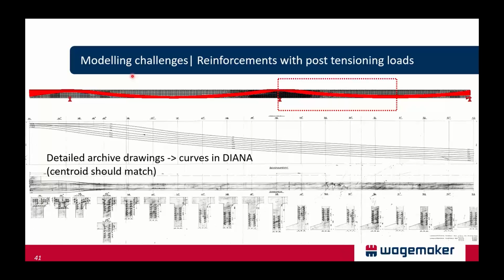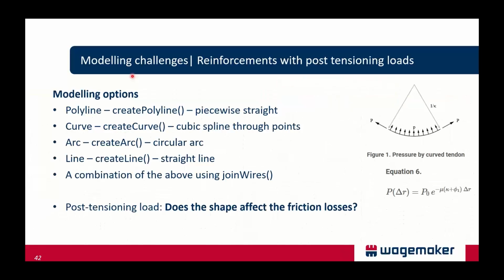If you put these curves in Diana, or put these individual tendons in Diana, you want to do it as accurately as possible. At least the centroid at each location should match the archive drawings, but preferably the actual location of the cables should be as realistic as possible.